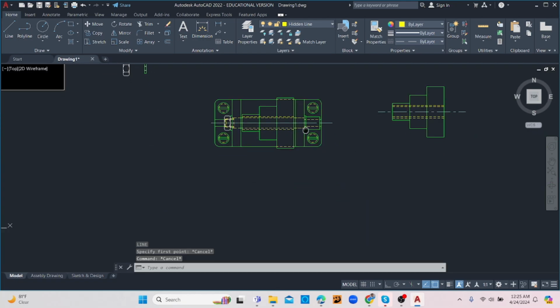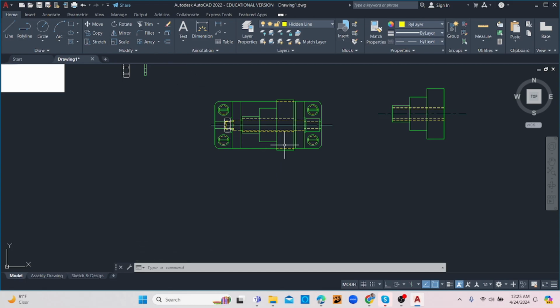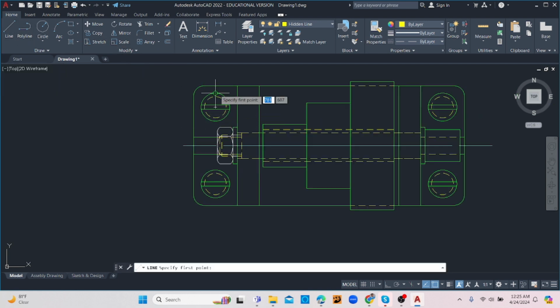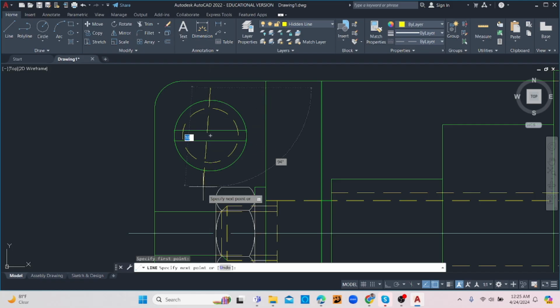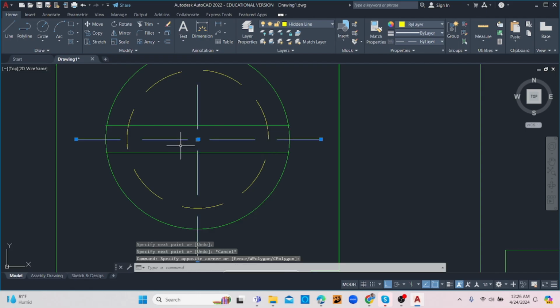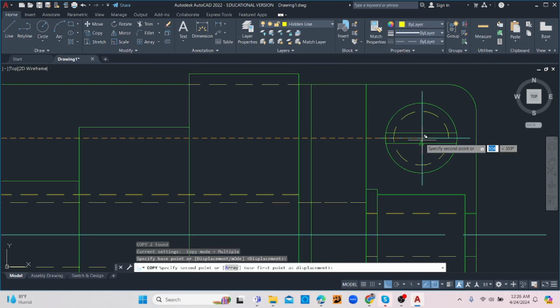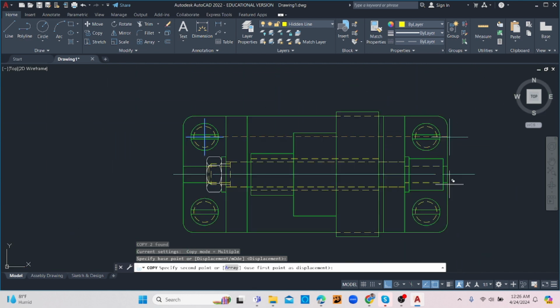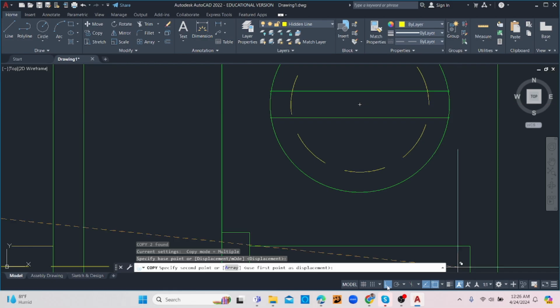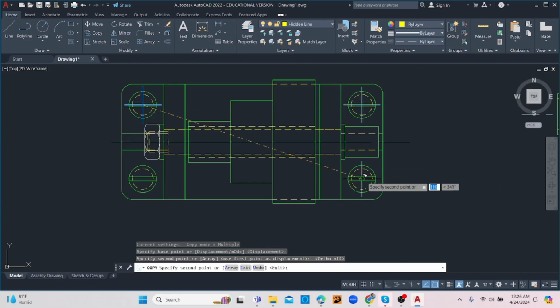So this is the plan view. Alright, and you can sort that out in terms of dimensions and such. Put in your center line. So where would center lines be? Center lines would be wherever there are circles. So for example here, and because these are 4, we can easily just copy them and place them to these locations as well. Let me turn off my ortho. Snapping there, snapping there, snapping there. Alright, we have the center one running down the center already.